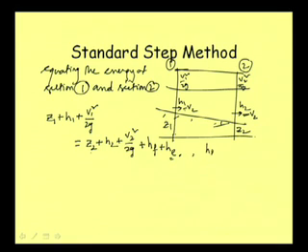That we can write, if this distance is delta x, then we can write this as SF into delta x. And then what is HE, the head loss? I am not drawing it here. I can draw a horizontal line, and the total loss we can divide into two parts. This part is HF and there is another part which is HE.